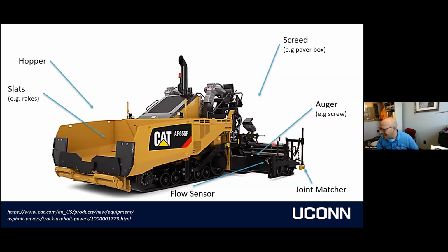So I thought I had an arrow that showed it, but it's a little hard to see because it's black. The screed is only connected to the paver right down here at the toe point. There's this long, heavy duty arm on both sides that goes back to that. The reason being is as the paver rocks or pitches over non-uniformities on the underlying ground it's traveling on, we want the screed to be a little immune to that, which is a good thing.